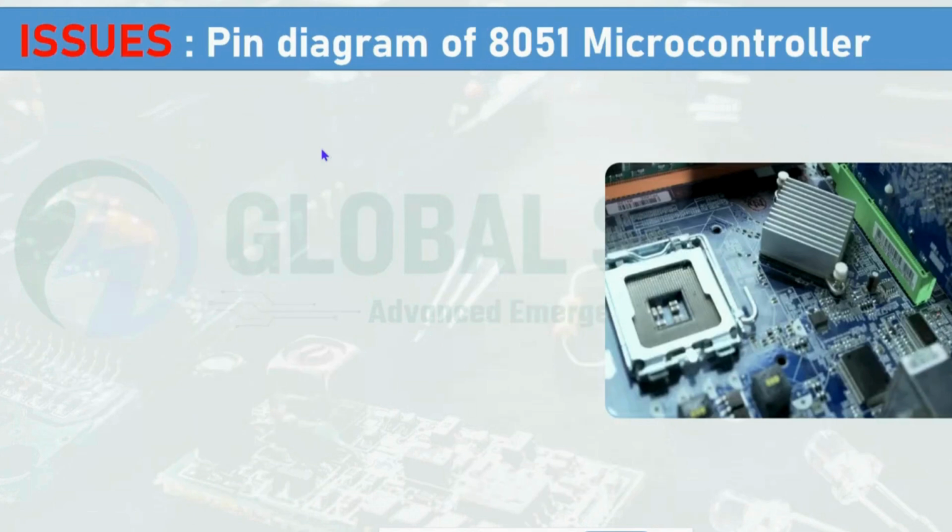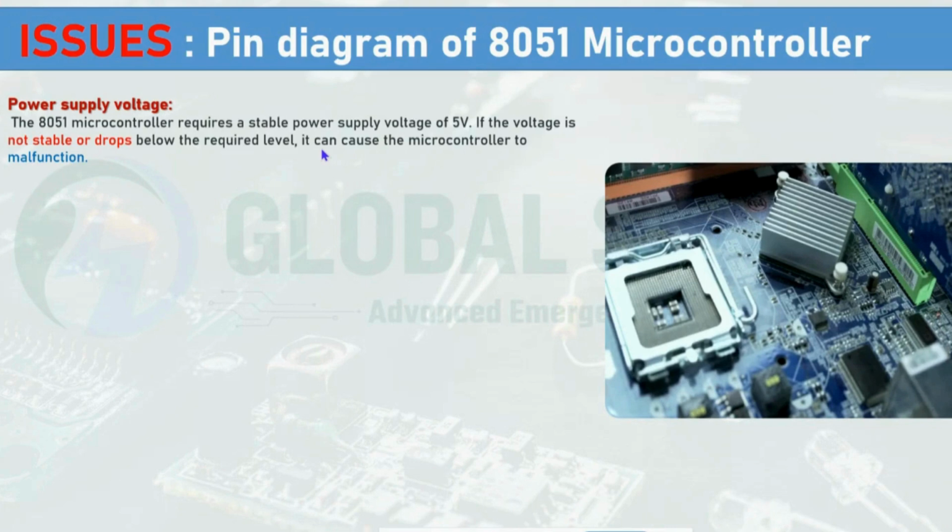And what are the issues you will face with the 8051 microcontroller? Initially, that is part of the power supply. Usually, it should be operated with a 5 volt supply. If it is not stable, the microcontroller won't give proper data.